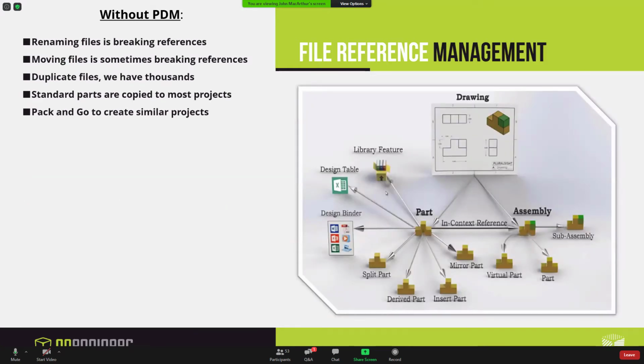All right. Well, here's the deal. When you're moving stuff around, when you're changing names, sounds like with the PDM, I don't need to change names so much, but there is an organization level that we might get into. Once again, I don't know where parts are going to lie. I might have parts in one area, another area might have a working directory. So when we rename the files, the references are broken. It's easy enough to connect that together, but when you're talking about hundreds of components in an assembly, that could get ugly. Moving the files around, once again, we can do it. There's tools in SOLIDWORKS to help you do it too, but sometimes it's easier just to move it and let SOLIDWORKS ask where they're at.